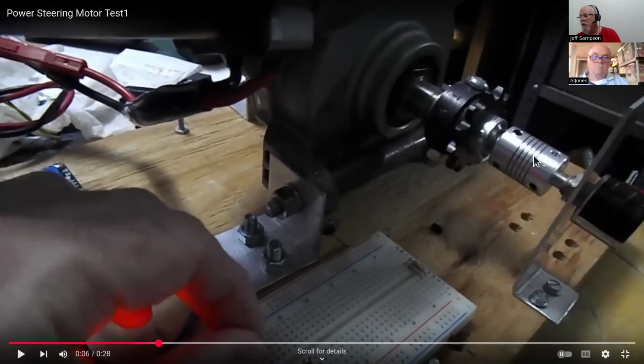And the important thing I wanted to show here was, as the motor's moving, you hear this funny squealing sound, and that is the noise from the PWM signal that comes into it. Because if you're running the Arduino AnalogWrite command, it has a fixed frequency of approximately 500 hertz, and that's the noise you can hear.